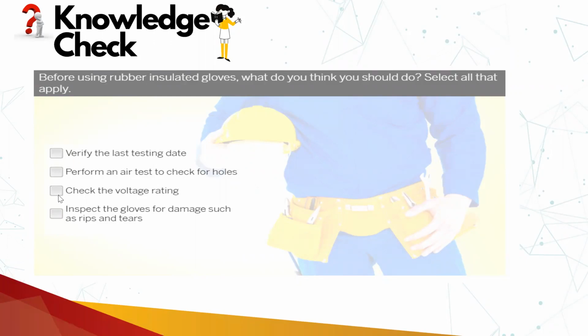Yeah, verify the last testing date, perform an air test to check for holes, check the voltage rating, and inspect the gloves for damage such as rips or tears. So all are correct. A, B, C, D, all four are the right options.